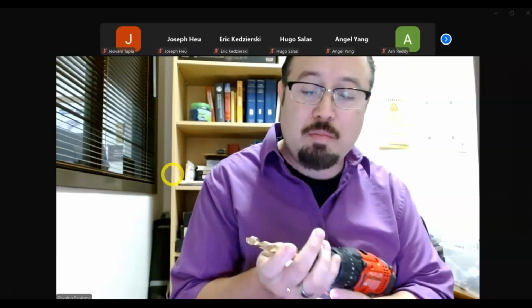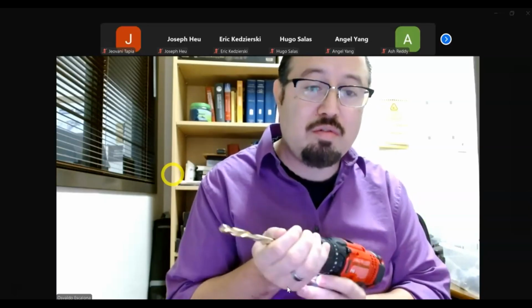If I go the other way, forwards, and I press the start button, you guys will notice the chuck closes. Really easy. Boom, open. You open the chuck, you grab your drill bit, and you stick it there. When you grab your drill bit, don't put your fingers on the flutes, and also don't hold it too hard. You don't need to hold it too hard.